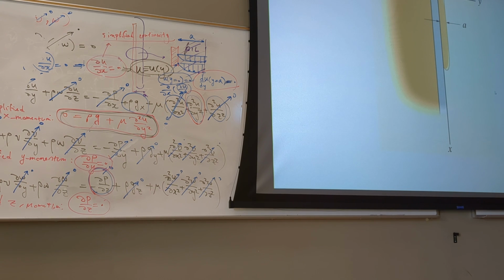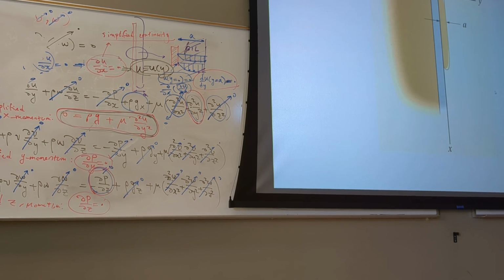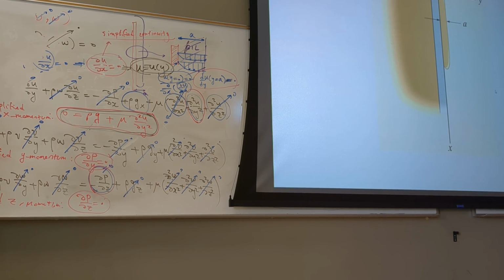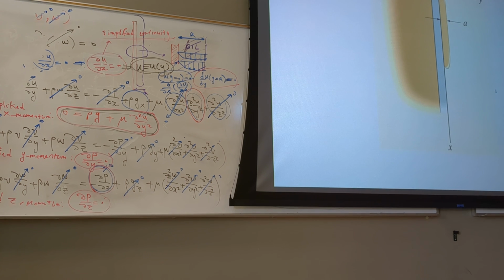Well, I forgot to put the result from the book, but it must be this. Do you have the book? Can you check? Let me simplify that. You can factor out this term. So you can write u of y is equal to rho g over mu times (a y minus y squared over 2). All right, it must be this.